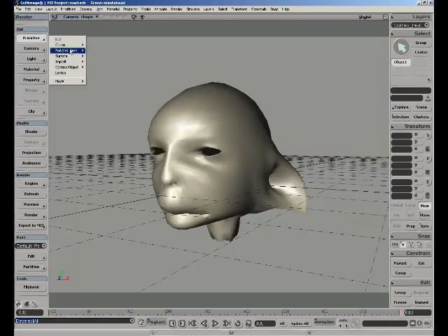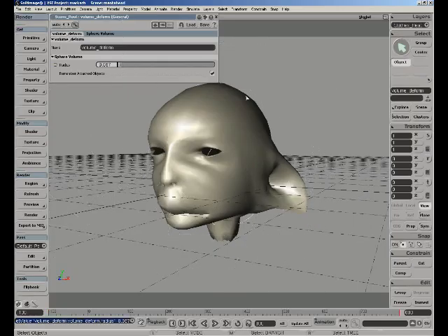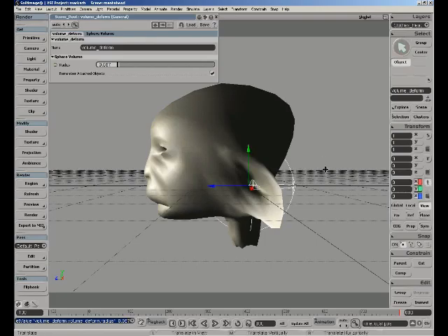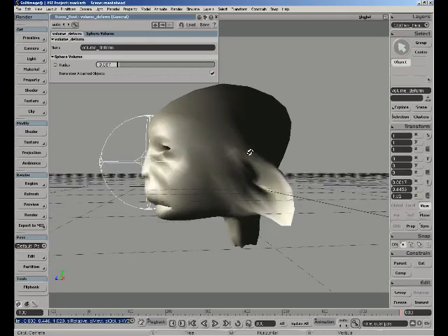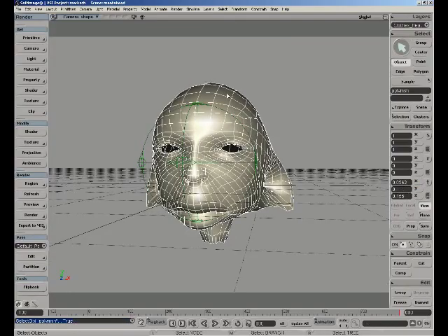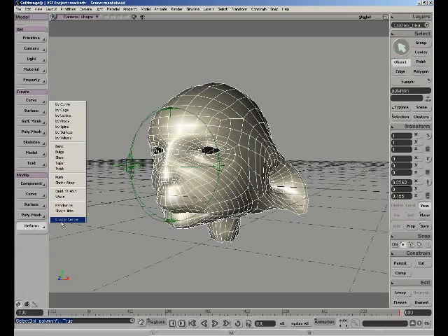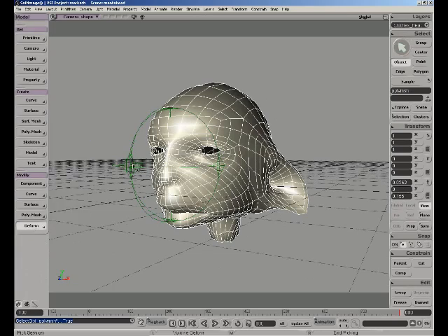A new control object type can be found, and here it is. It's called the volume deform. So I'm just going to select that, scale it down to about here, and now let's position it here near the front of our character. So we'll close this up, select the geometry that you'd like to apply the deformer to, and then simply deform by volume.